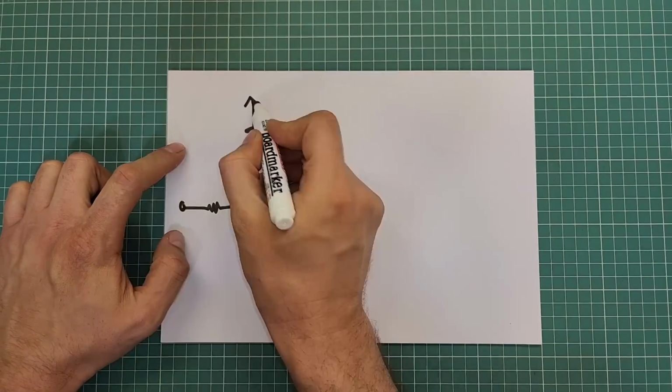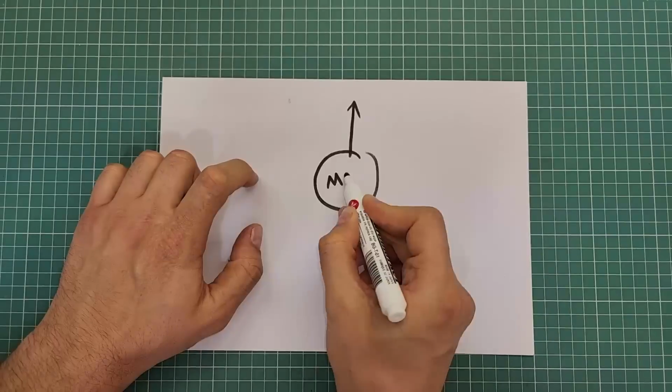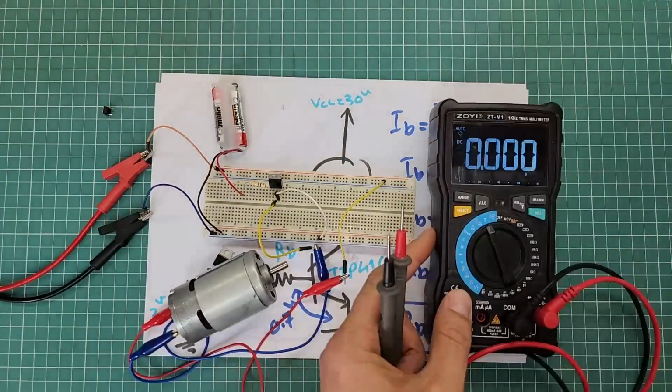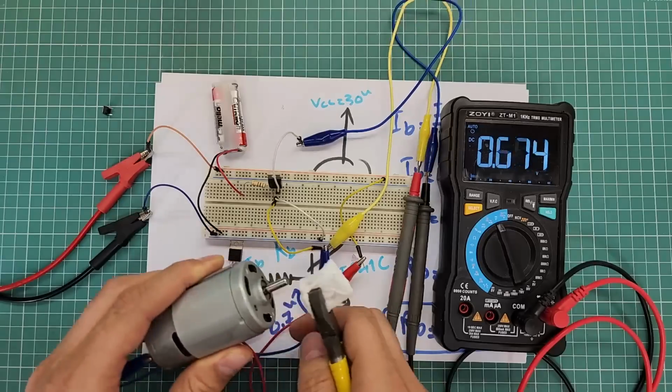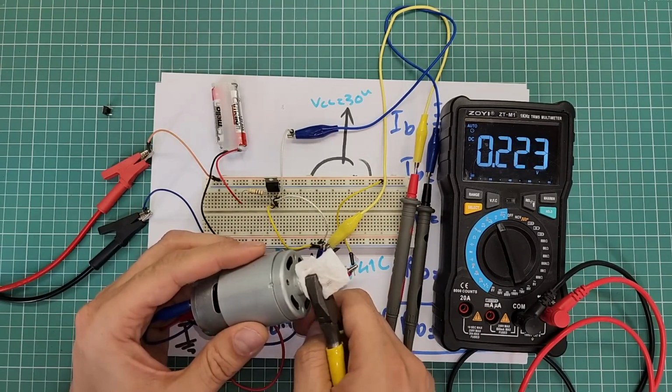In this video, I'm gonna tell you why we have to put a resistor at the base terminal of a transistor and why its value is important. Then I will teach you two approaches, a simplified method and an advanced one, to select the best base resistor value. Also, we will explore the data and graphs on the datasheet to find the information to select the best base resistor value. Please stay with me until the end of this video.